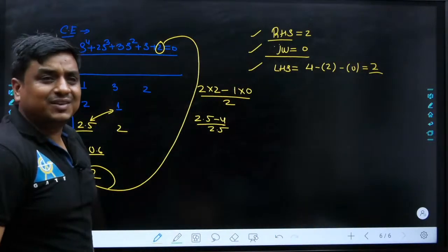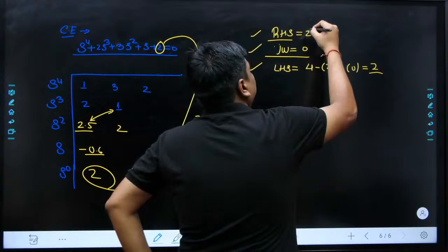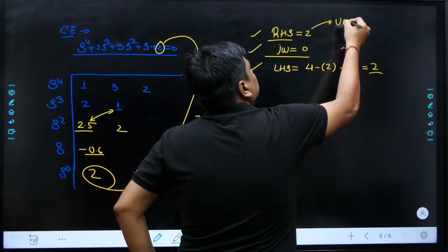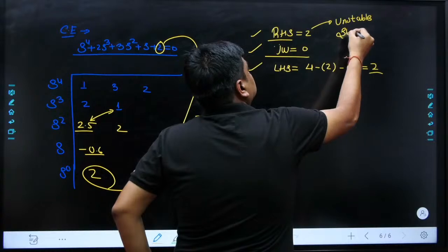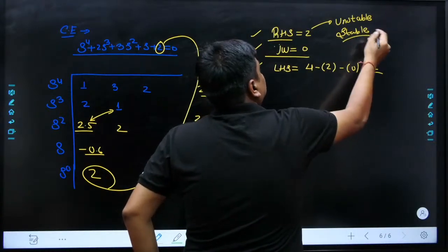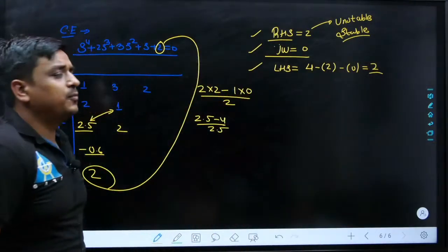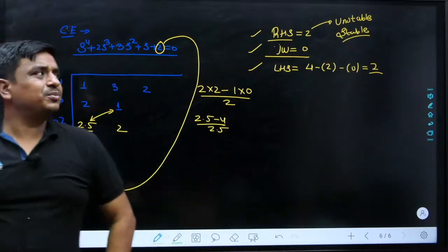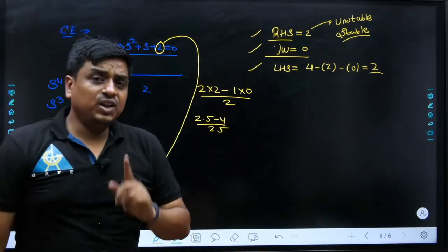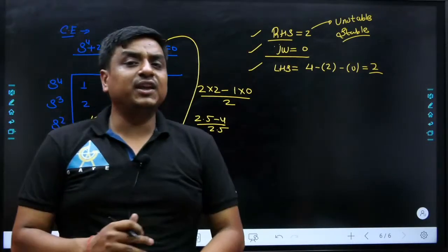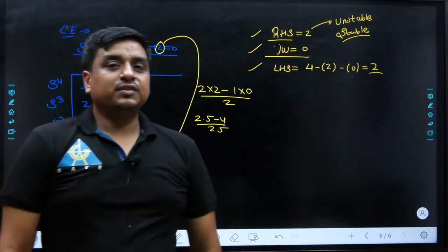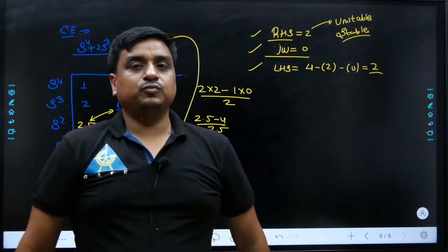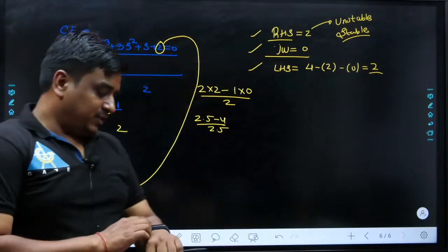Although if we talk about the system's stability, the system is already an unstable system. Could you understand why it's an unstable system? You can see very well, my dear friend. If any of the closed loop poles goes towards the right hand side of the S plane, taking the reference of the j omega axis, the system becomes an unstable system. Agreed? Agreed?